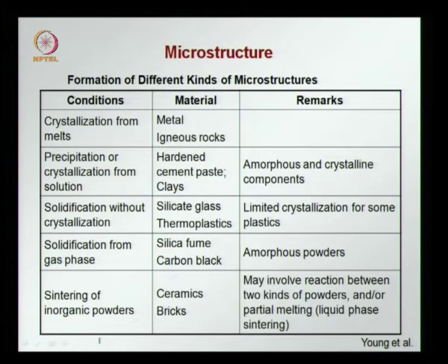You can also have solidification without any crystallization, like in the case of glasses or thermoplastics. Silicate glass forms without crystallization through solidification. You can have limited crystallization for some plastics, that is, some plastics can have some amount of crystallinity, the rest would be amorphous. This is again something that we looked at a couple of lectures back.